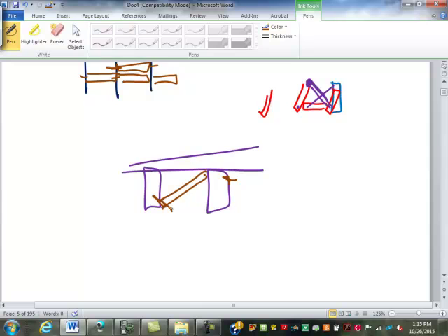Some people just say as long as you nail it here, you don't need to nail it here because it's just going to push into that. And there is some truth to that. But the problem is, let's say this piece falls out. Well, then now this starts to move and it'll pull away. So having it nailed here does help. One of those has two pieces, doesn't it? Yeah, it's going to be two pieces.